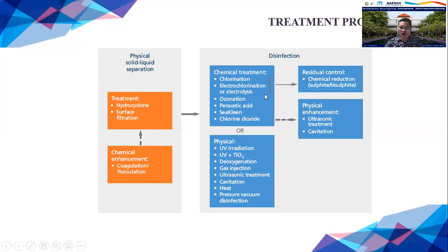So if you see this one, there are so many technologies already offered to treat the ballast water. But bearing in mind, two steps have to be conducted. It's not possible with only one, but the solid-liquid separation shall be conducted, because as you know, the treatment is not only for ballast water, but also for the sediment of the ballast water.